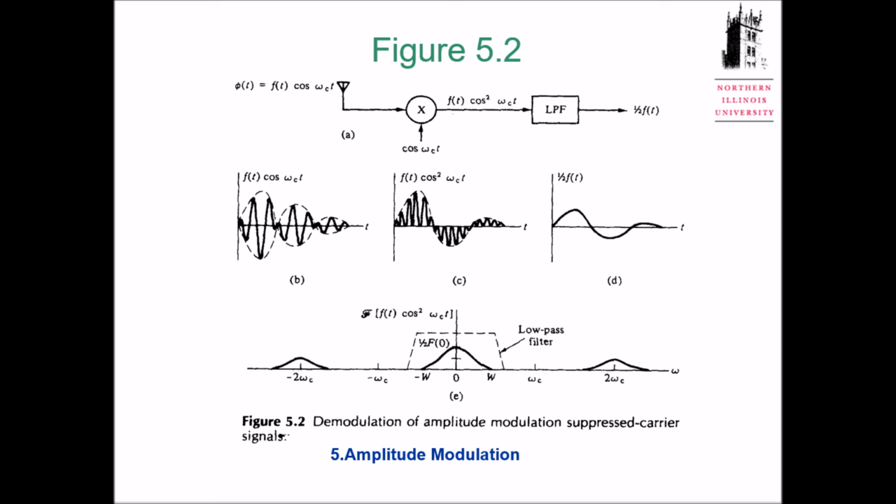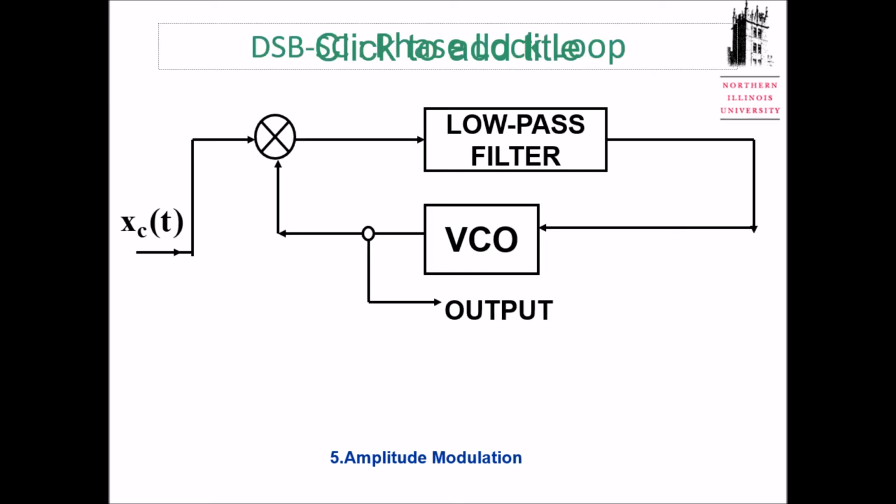Okay. But from the block diagram we know the control signal we use will be the difference, right? So after mix and low pass filter, the difference between the input and the output of your VCO will be used to control this VCO. So we believe that when my input is very, very small, I can just stop changing my frequency. Okay, it's like negative feedback. Yes, negative feedback. And for VCO, general concept will be F, right?